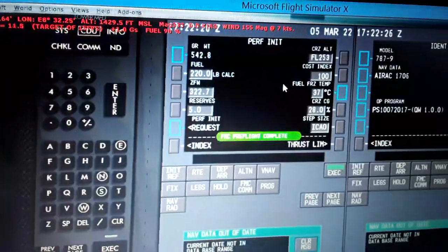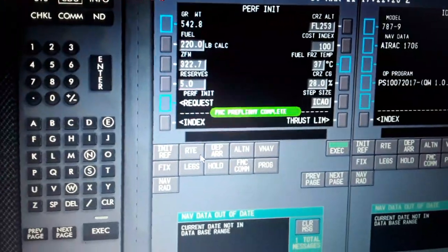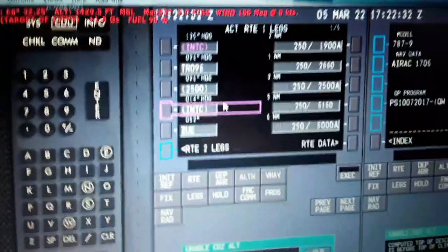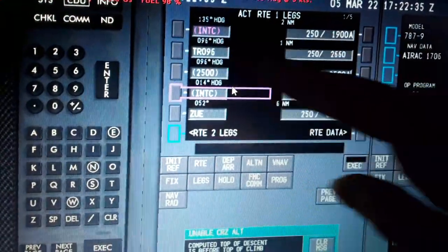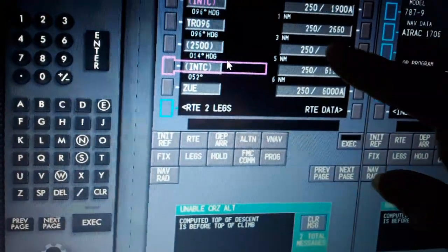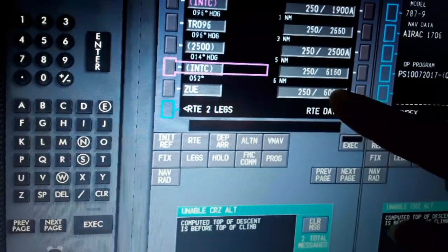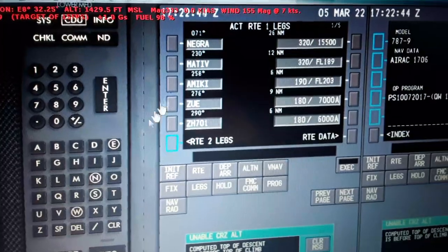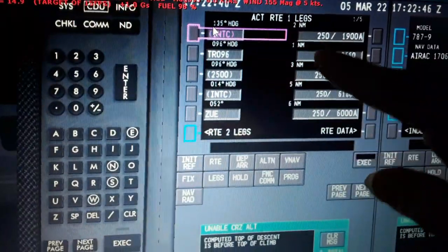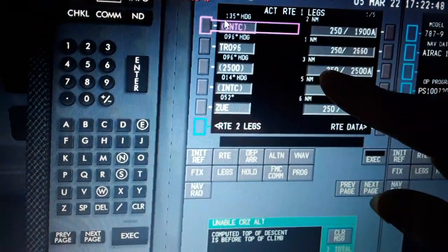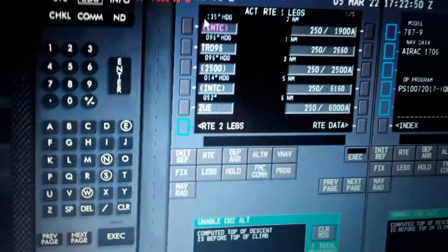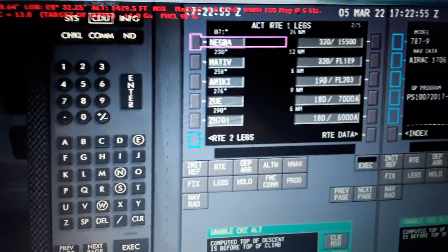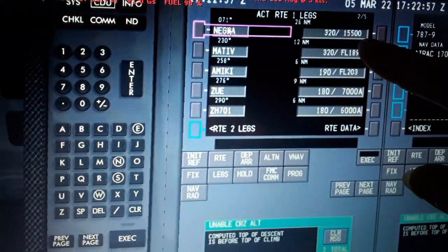So we have the request of the flight plan we can execute over here. It will give us the first waypoint, second one, the airspeed, also altitude, the ZUE 6 nautical miles, 250 knots, 6000. Then climb, we make a turn. This is the runway heading, a few nautical miles, 1, 3, 5, 6. Then we make a turn 071 degrees, 26 nautical miles from Zurich, 320 knots.